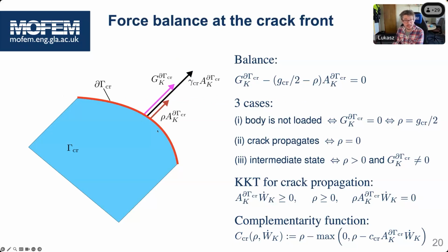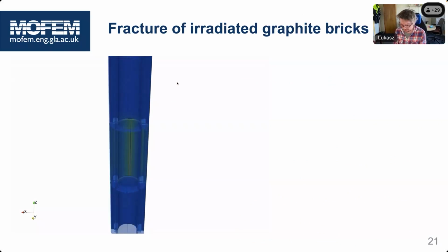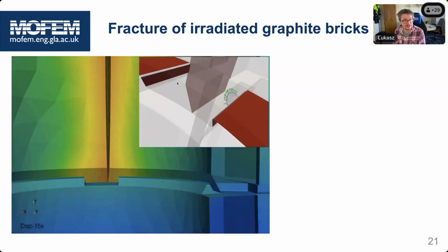In our formulation for crack propagation, we calculate crack front equilibrium directly, implicitly on the mesh, and we have this complementary function: when the Griffith energy at the nodes is equal to the material resistance, the crack is moving until the new equilibrium is established in implicit form. That is a very complex analysis, strongly nonlinear because it's on an evolving topology. But despite that, we can yield results which match the physical reality.